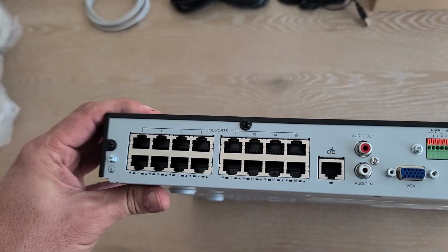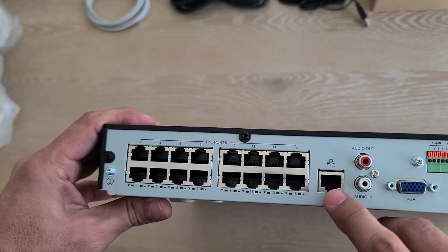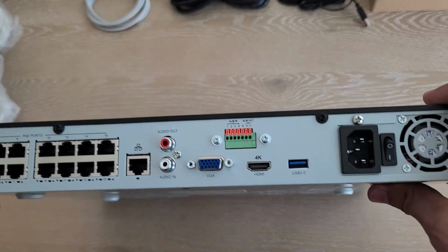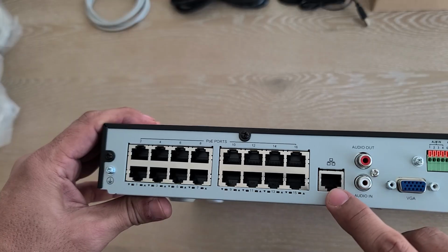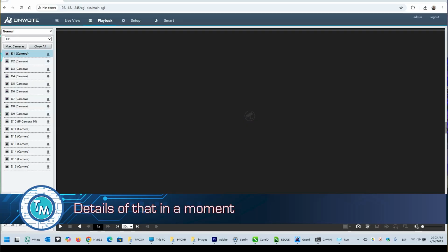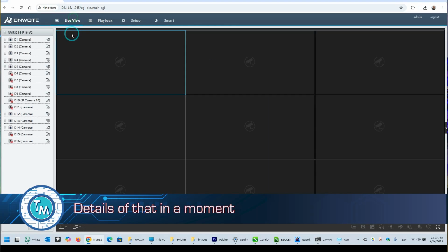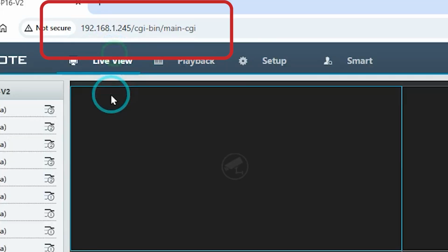This switch performs address translation just like a router does and will connect to our local network through an independent port. The total consumption of a system like this one without a monitor is around 40 watts with all the cameras. This so you can get an idea. The address that this local port receives will be the address to which we will connect when we install the client program on any computer in our network from where we want to monitor.